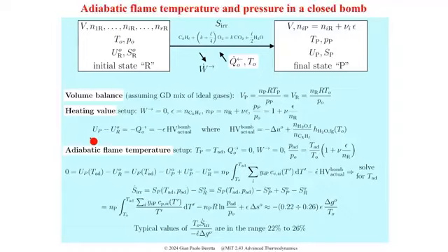Okay, so if you do the energy balance, you get the heating value, and the heating value this time in this setup is equal not to the enthalpy but the internal energy of combustion plus the amount of energy that is involved in condensation, and I presume that here I should change this into a U. That's the internal energy of condensation, and not the enthalpy.